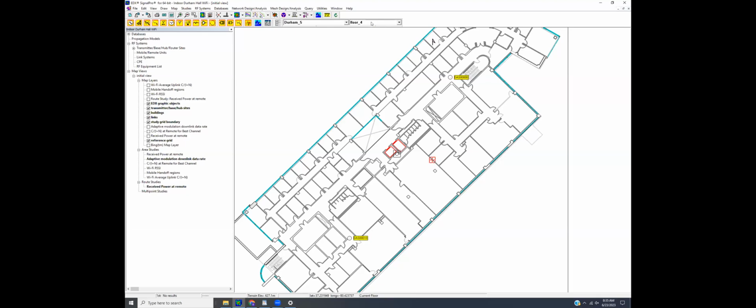So in other words, the AutoCAD drawings of each floor plan, we imported those, cleaned them up a little bit using our building editor tool. So I would start here with building editor, import those floors from DWG and create this building model. And the main thing there is taking out extraneous stuff that might be in that floor plan drawing. Like, for example, this staircase here, I don't want each of those stairs and the arrows and stuff to be regarded as solid walls. So we have a tool in the building editor to just throw all those items into a group and set them to an RF transparent reference material type so that they don't interact with RF. They're just part of the picture that we see.